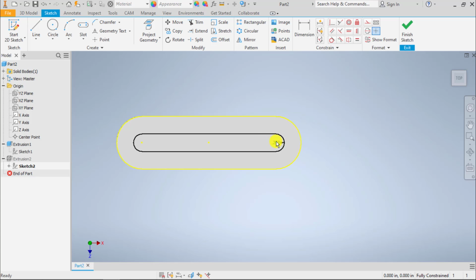But if you remember in the Modify Tools video, when we offset this geometry, we wanted the distance between these two to be driven so that if I change that size, let's say of our first extrusion, it will maintain that distance. So if this is an inch from center to center, 3 inches, or a mile, it will always maintain this spacing. This is not the case anymore when I do it like this.